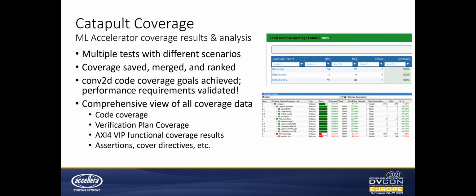If you recall from a few slides ago, there was an overall requirement that this design be able to perform at least 1 inference per second. Early simulations of an initial design implementation revealed that we were way off here, something like 14 seconds for an inference, requiring some very early design re-architecture. And again, the simulation performance benefits of targeting our pre-HLS design is what enabled these sorts of early analyses. Subsequent design architectures got our performance down to under 3 seconds per inference, and then refinements to that design ultimately got us underneath our 1 second per inference goal.